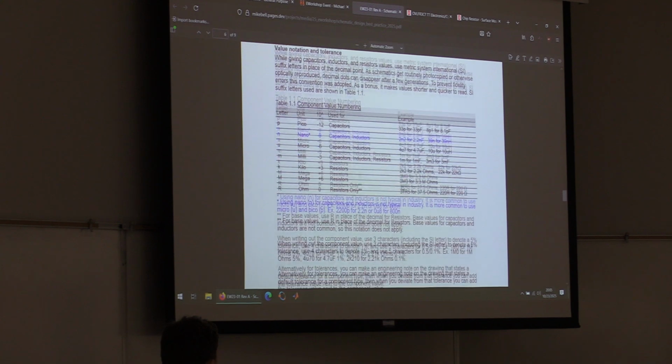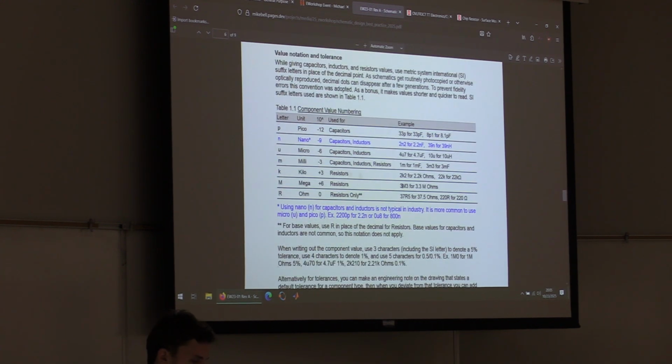And then covering, this one's regarding the way we write down component values. So in this case, for a 10K resistor, 10,000 ohm resistor, we usually do 10K. And sometimes we actually put that SI unit prefix where the decimal place is, just so that it's easier to read and harder to sort of get confused on.